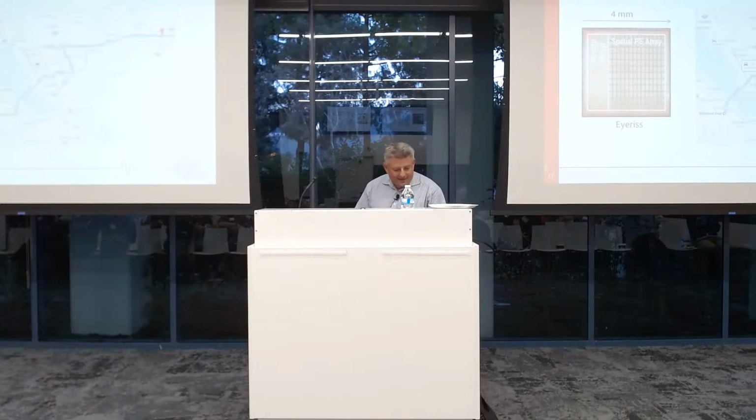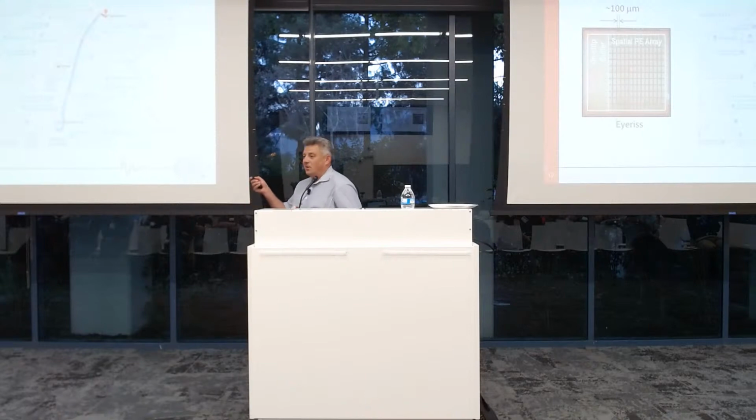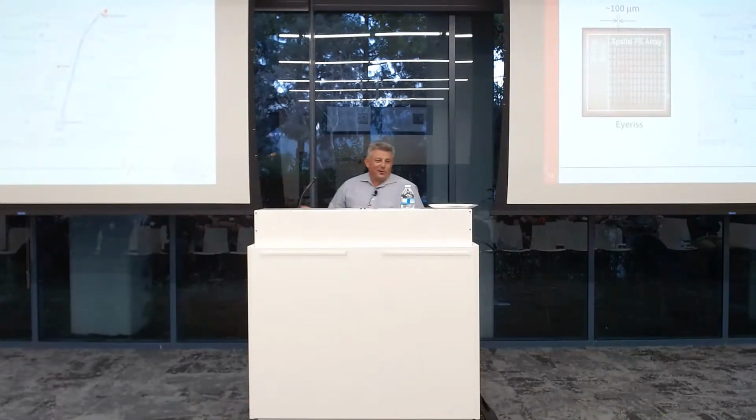On the other hand, inside the processing array there's a little bit of register file. If you want to go from the register file to the compute unit, to the multiplier or the adder, that's a shorter trip, maybe 100 microns. Scaled to the car, that's from the Stanford Oval to the sports bar. So I prefer that trip, right?